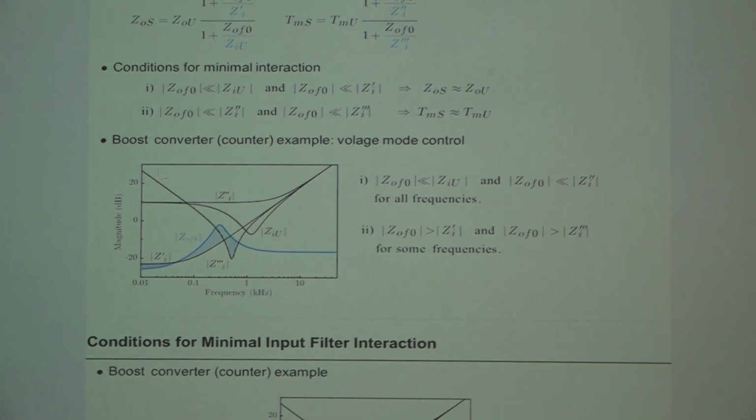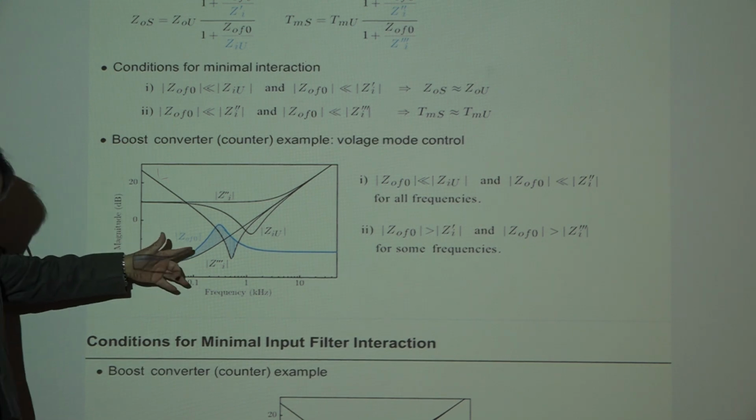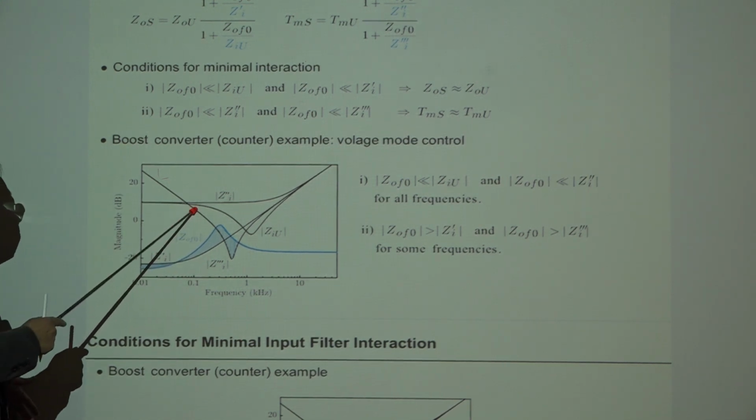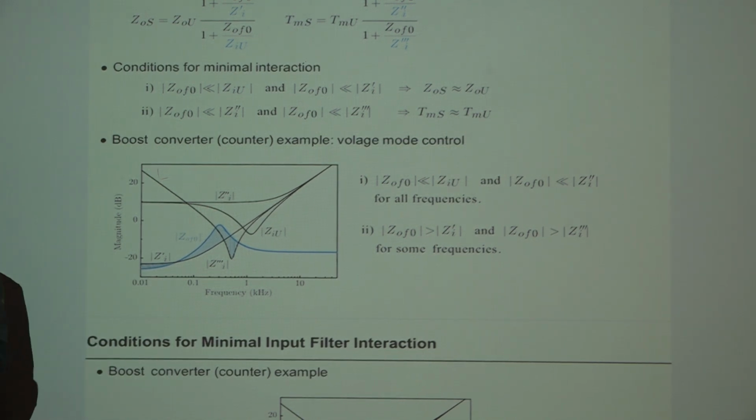Because we are talking about the impedance, it can be boosted, but this is the open loop system. So this is not controlled because this is only determined by power stage parameters, because the feedback loop is opened, right? So this is the general result of just using the open loop situation, okay? All right. So this is very important. These two are closed loop input impedance.